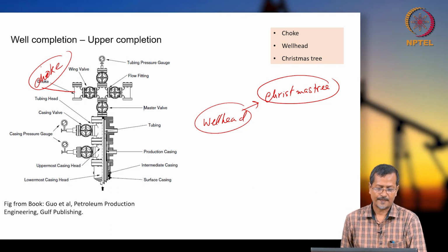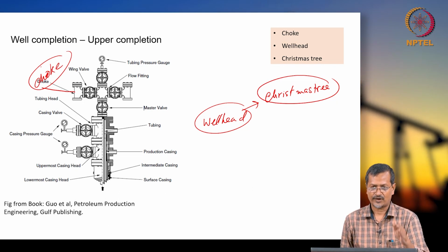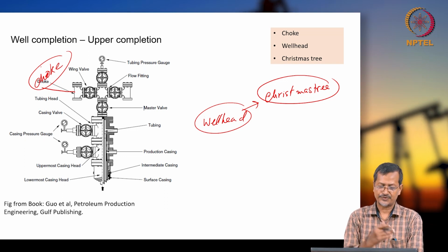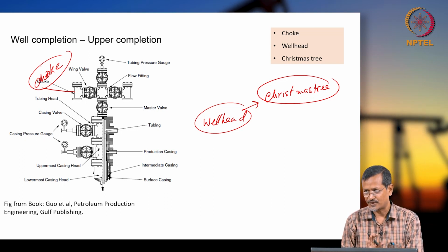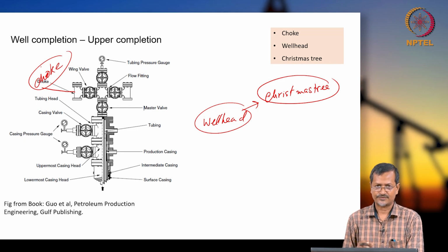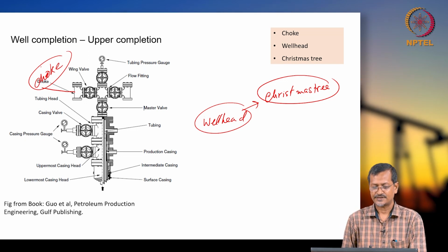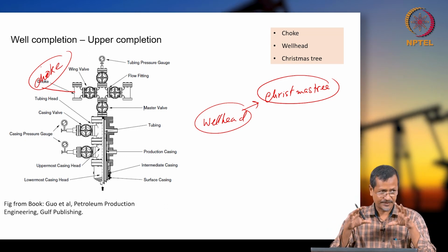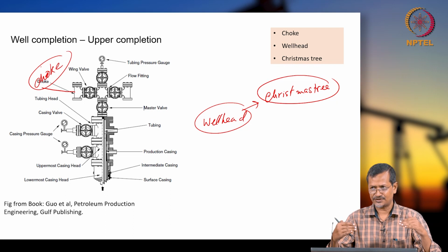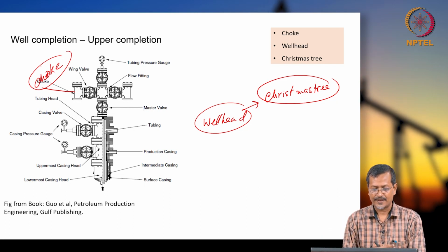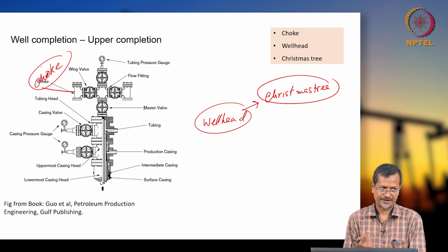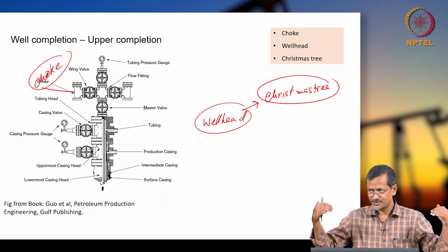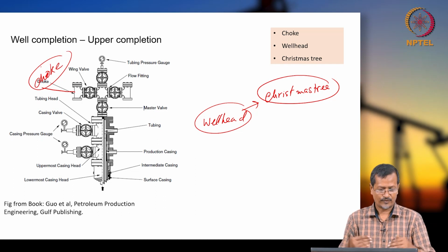And that is one important part for the oil industry, because if you do not have a choke, then whatever flow you are getting, you are producing, that can create an unstable production rate. Unstable production rate means, say you have a sand control system and everything is stable, less sand is getting produced, no water coning is happening, and suddenly you change your production rate. In that case, maybe more sand will come into the wellbore, or maybe water coning will happen.